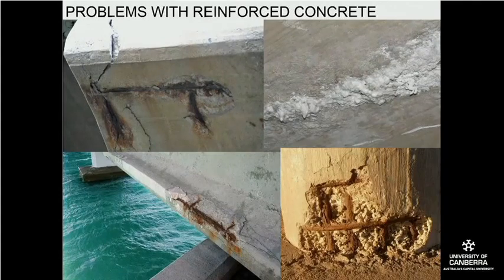Typically in older apartments, like 60s apartments which are throughout Canberra, they used to make concrete bases purely out of concrete and without any sort of plastic waterproofing like we use today. And theoretically, the more cement you put into a concrete, the more waterproof it gets. But the problem is that because it's handled by humans in a changeable environment, it's not an ideal laboratory situation, so things do happen, and it happens quite often.